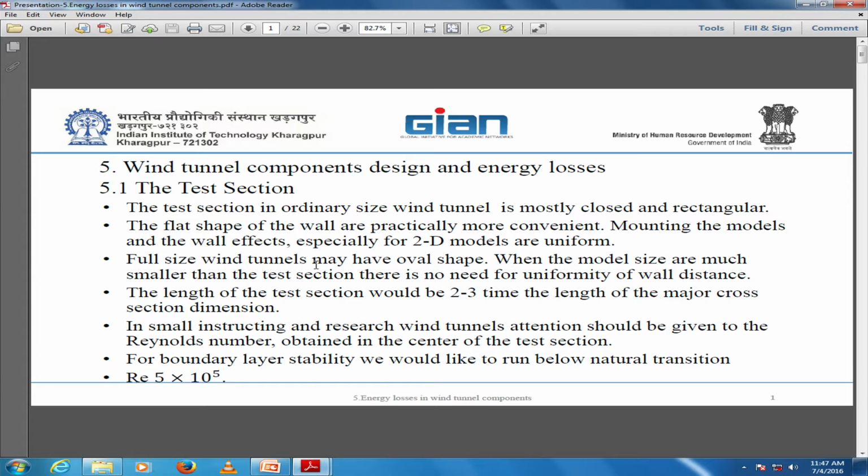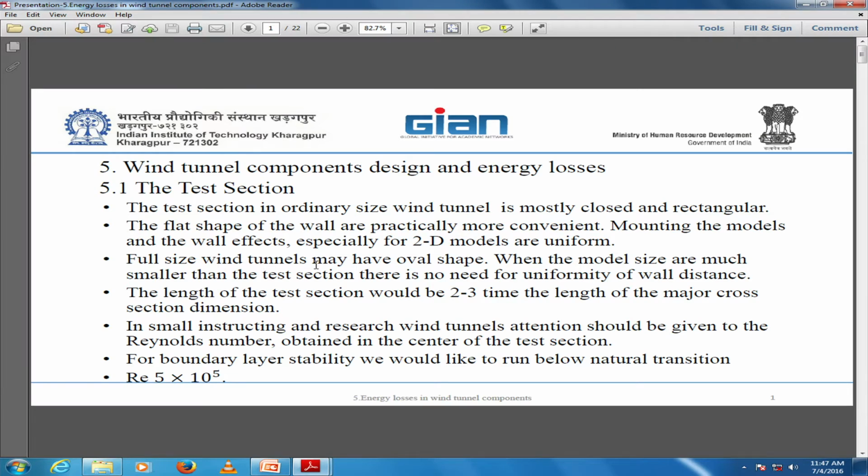Roughly, the comparison between the loss of closed test section to open test section, you see 3.5 versus 20% for the open test section. And you have this correlation formula to calculate your loss factor there. I don't see where I'm using this relative Reynolds number between the local and the test section, putting in the area ratios and Mach number.